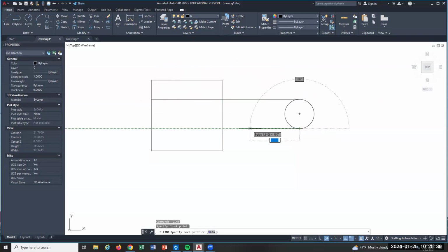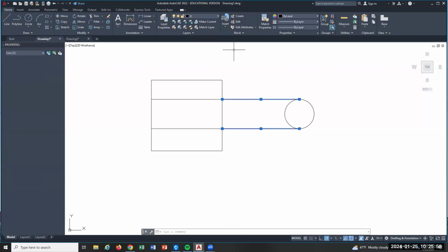I'm watching my object snaps carefully. So that's intersection, that X. So I nail it. And then this green line's going, so that's good. And an X. So that's good. So this is a line. See how it highlights? Everyone see that? Yeah. And this is a line. So these are my projection construction lines. Yeah. Well, I don't want them.